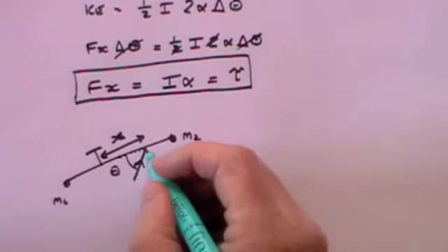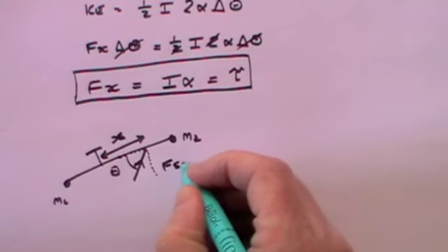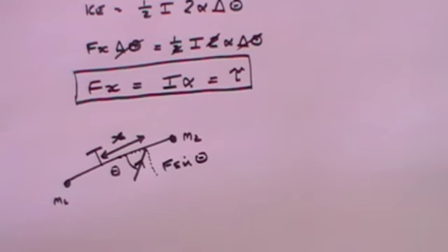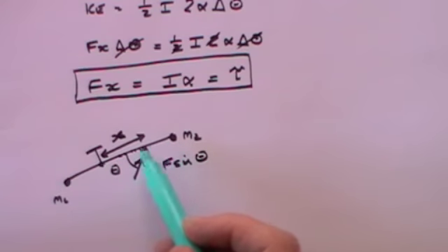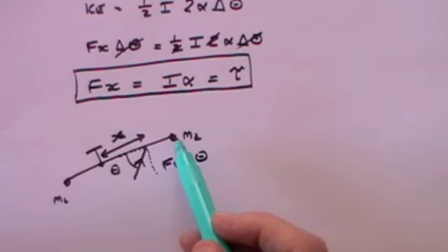This one, which is the one that's perpendicular, is F sine theta. There'll be another force, F cosine theta, acting along the rod. In fact, it will be pushing the rod away from the pivot point. And that is completely wasted, because as long as the pivot point is strong enough, pushing away from the pivot point along the rod achieves nothing.